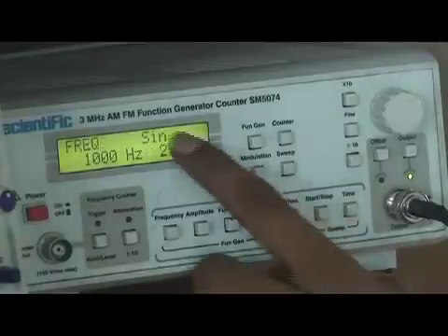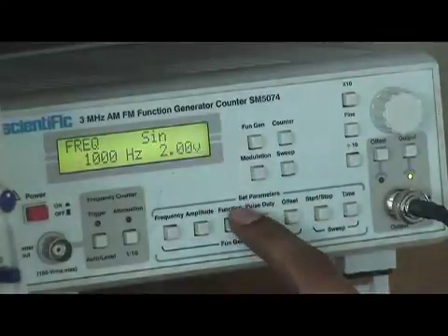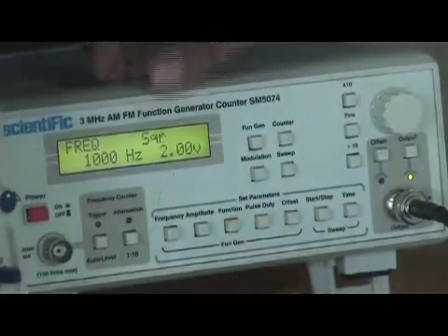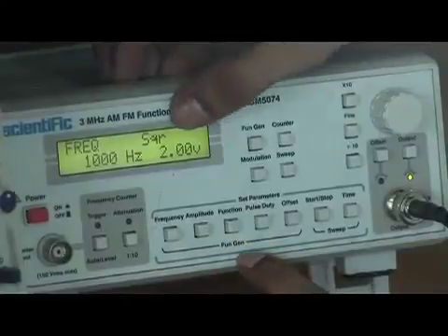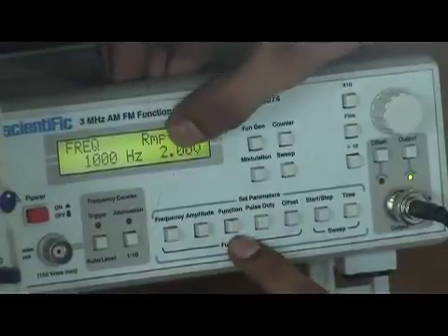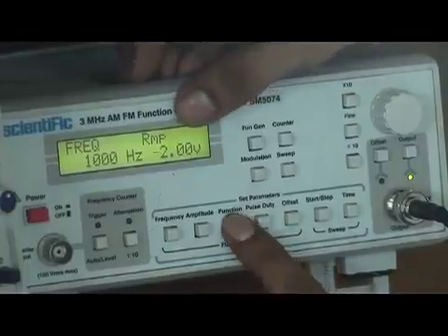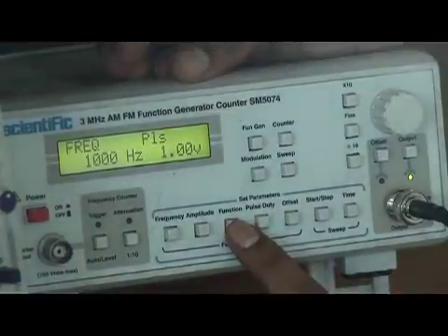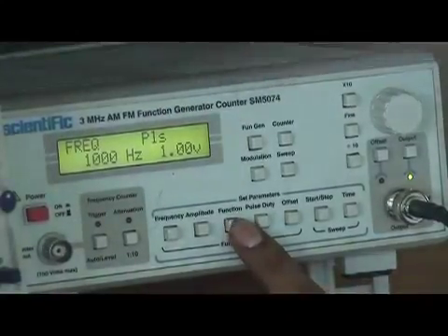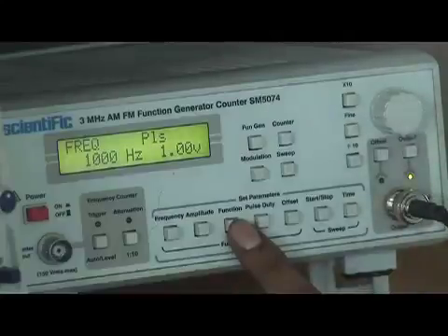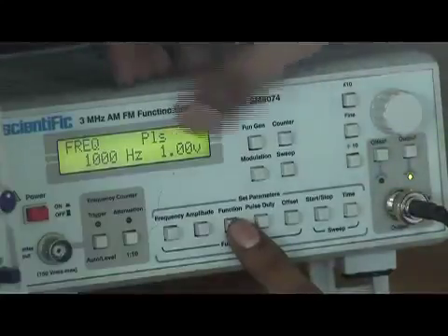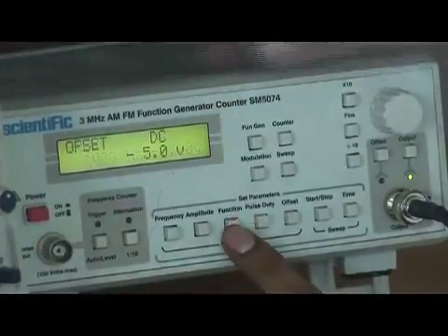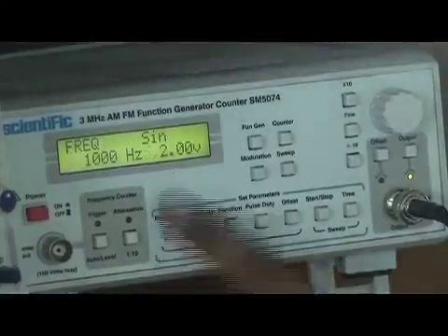Now what is the function? My function is sinusoidal. You can change the function from sinusoidal to various functions like triangular. If you press it again, square. If you press it again, again a square. Ramp, it's 2 volts. Ramp minus 2 volts means a negative ramp. This is pulse 1 volt, because when we say pulse, it denotes only from the reference to the upper level or from the reference to the below level. When I press it again, it says a pulse of minus 1 volt, meaning below. Then a DC voltage, then again back to the sinusoid.